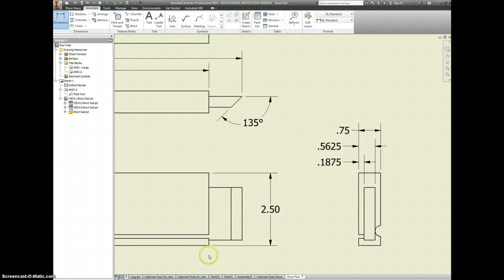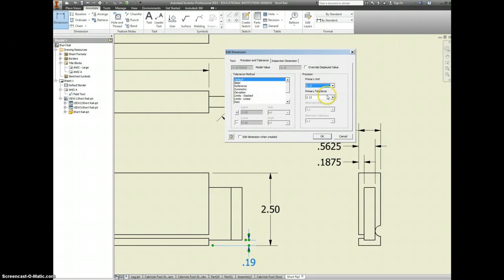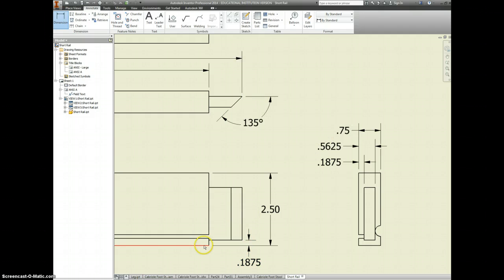What else are we dimensioning? Well, with this view, I'm going to call this bottom part here the datum. That number doesn't look right. That goes out 4. Let's call that another datum, which means this will look better if we pull it out just a bit, maybe up some too, where they're not running into each other.